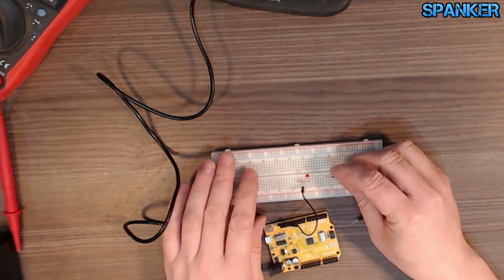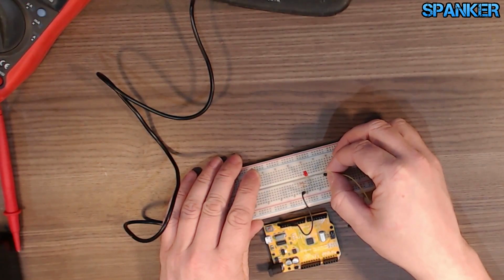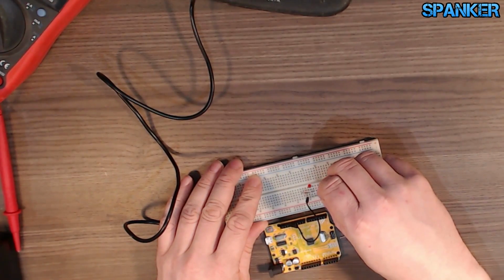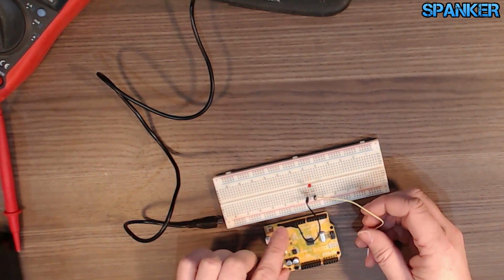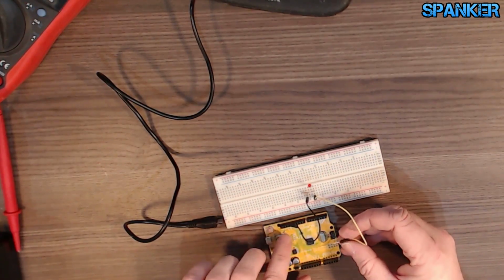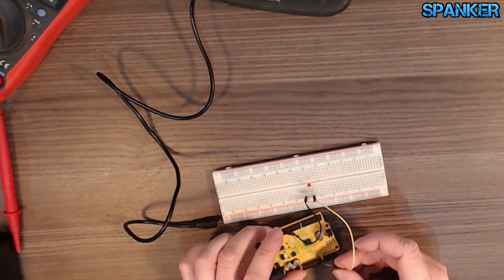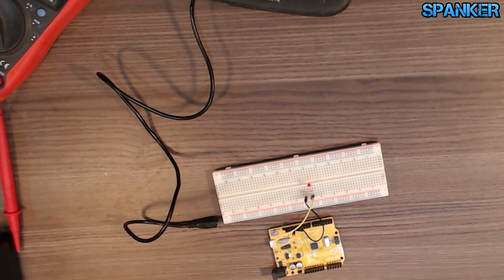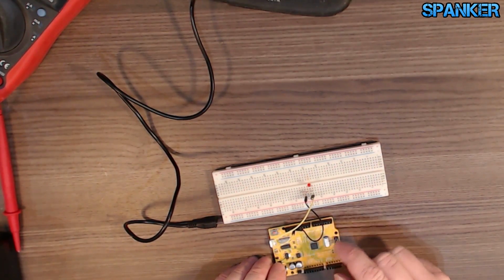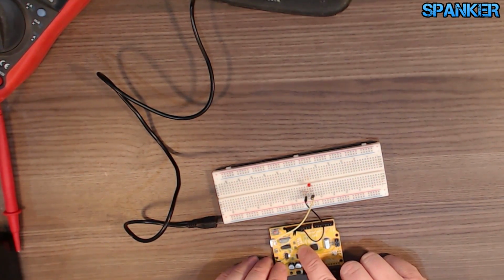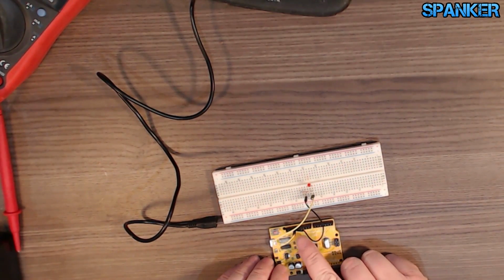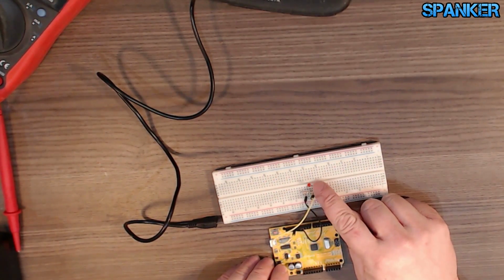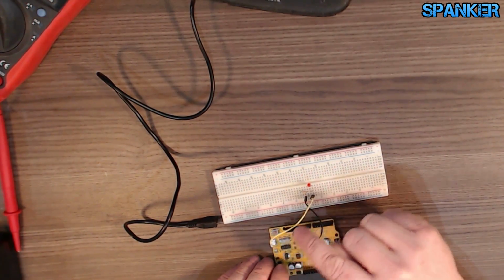Then we follow that track of the second leg, the negative leg. Plug another cable in there, and we're going to find somewhere on the board a ground. So there's a ground here, right next to pin 13. There's 2 grounds over here. I'm just going to bob it into that one next to pin 13. So because pin 13 is the same output as the built-in LED, every second it's going to send power down that line, through that resistor, through that LED, back up and back to ground. So it makes a circuit.